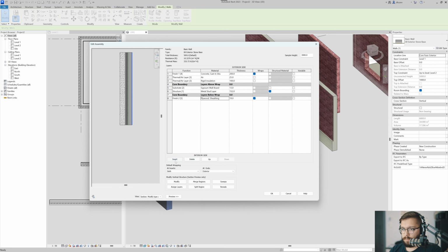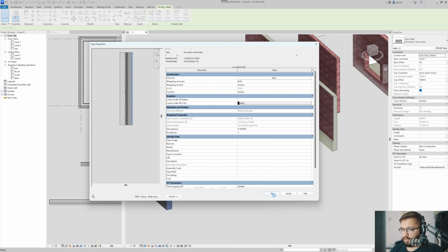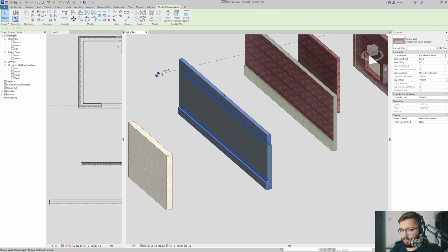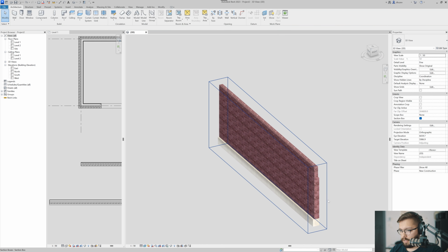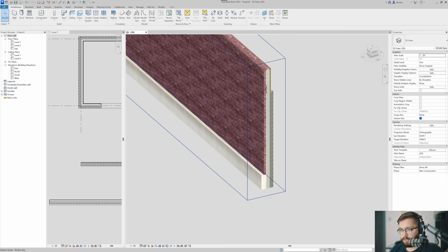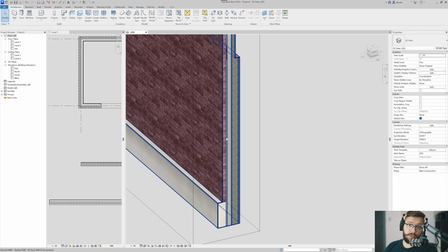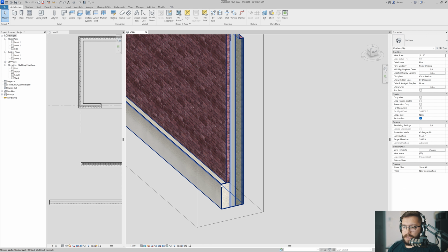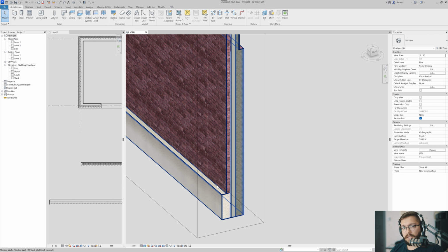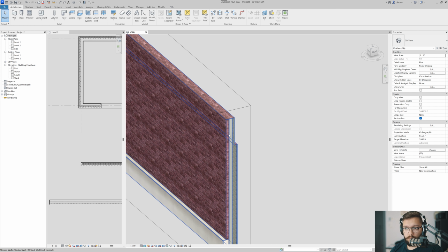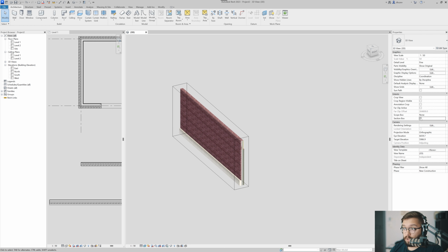So this would be insert. This would be gypsum wall board right there. We said it was 16 metal stud layer. Boom. And then this we said it was 22, right? So now we can actually match them. And if I do BX, so if I am able to cut through it, you would see that I have a continuous structure, which is precisely what I need. And I just have different things sticking out of it. And again, my parapet, which is smaller, because this is precisely what I want.